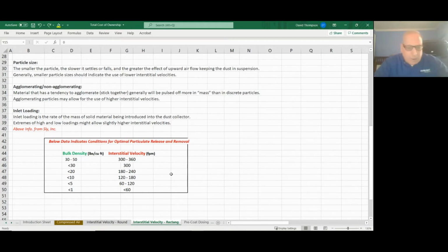90% of the baghouses that we go to where there's a problem and the bags are not cleaning properly or not lasting long, it's typically because they cannot evacuate the system properly. We find this a lot, especially in long bag technology, in bags that are 20 feet long and plus, or 25 to 30 feet long or more. Typically, they do not evacuate as well as they should. Typically, the bags will sit in ash or hot particulate material at the bottom of the baghouse and can't get out. That shortens the life of your bag, it reduces the amount of area you have for filtration, and it creates a real problem.